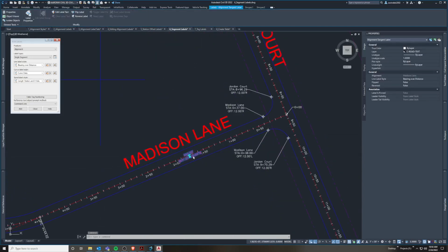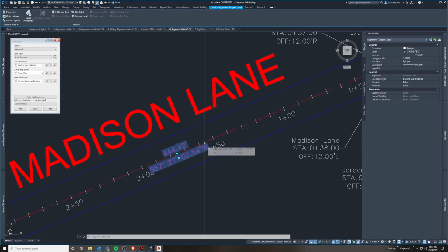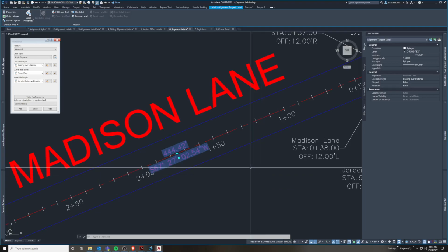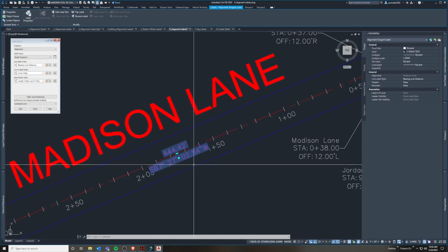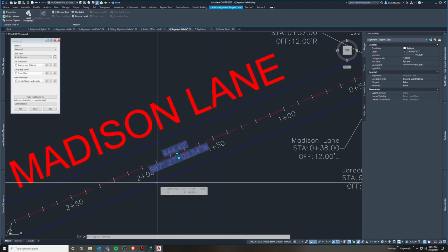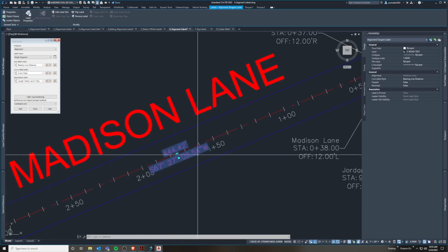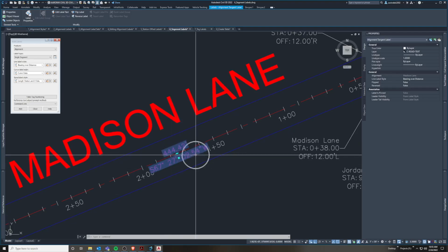Now, these are very common annotations in land surveying and civil engineering. The distance is given to the nearest hundredth of a foot, not in fractional inches like construction. And the direction is given as a bearing, which gives a cardinal direction, in this case southwest, in one of the four quadrants. Sometimes if it's straight north, south, east, or west, at 0 or 90, it might just say that. But in general, it has one of the four quadrants, and it's in degrees, minutes, and seconds to a fraction of a second.